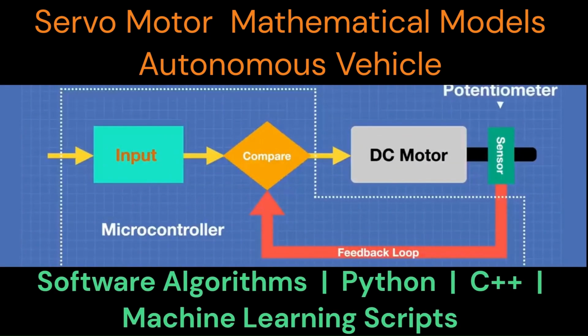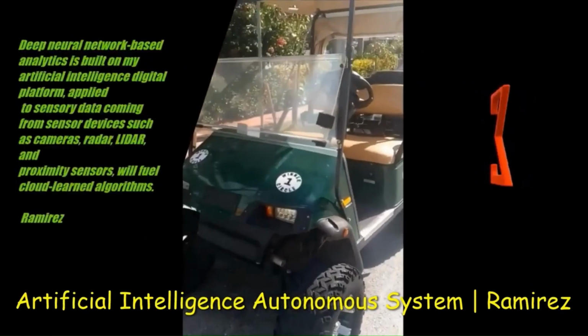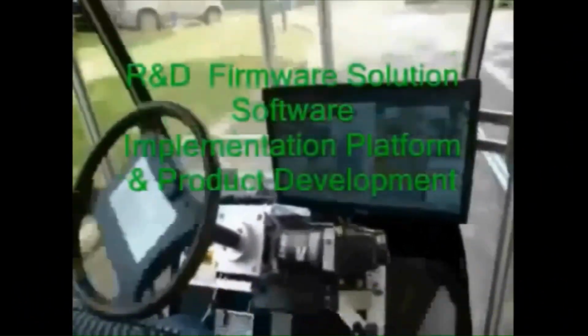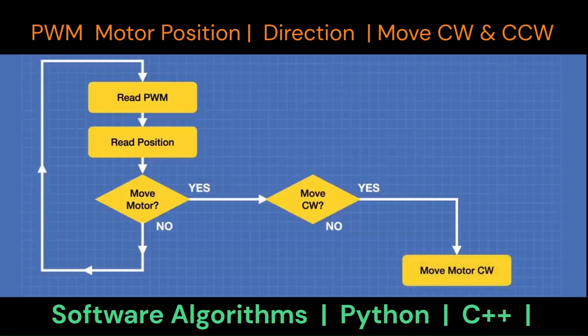So now let's define variables to hold the timestamps, which will be used to calculate the pulse width, and then define the pin number we are using to receive the pulse width modulation pulses, the PWM, from our servo controller.